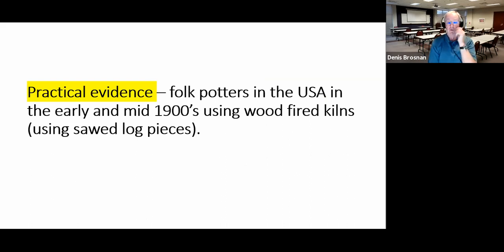And I realized that in the early 1900s, continuing on to the middle of the 20th century, they used wood-fired kilns. They had fireboxes where big pieces of wood, solid logs, were charged into the furnace to create the heat, and the heat from that fire went down a tunnel in an intermittent kiln and was drawn out by the chimney effect of a smokestack.